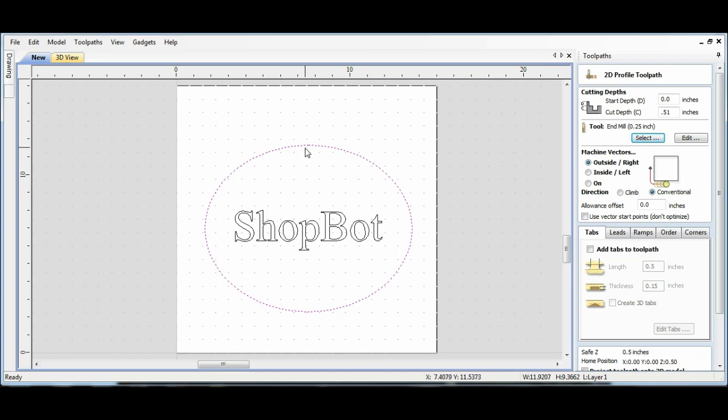So we need something to still hold this onto our piece of wood while it's cutting. Otherwise, as the router bit is coming around and removing the material, as soon as there's no more material holding this in, even though you would think it would just kind of be floating in there, wouldn't hurt anything, the vast majority of the time it's actually going to kick out. The piece of wood is going to slightly shift, and it's going to dig into your router bit, and it's going to cause problems, it's going to ruin your piece.